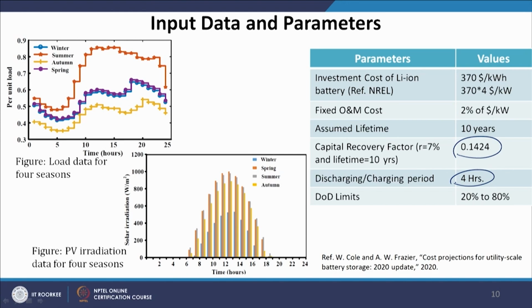So, what I wanted to highlight here, now you can consider different load patterns. All of you please try to understand, the load pattern of a particular system keeps on changing depending upon different hours of the day as well as different seasons of the year. Means during summer the load pattern is different, during winter the load pattern is different, but when you put a battery technology into your network, you cannot take it back again. So, once it is there, it is there. So, you have to see that for any load profile depending upon summer, winter or any weather condition, the storage device is really delivering its best.